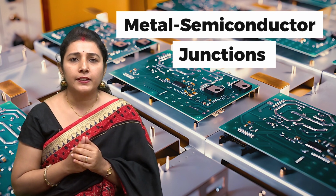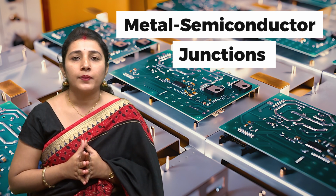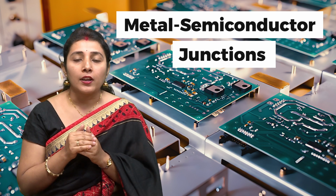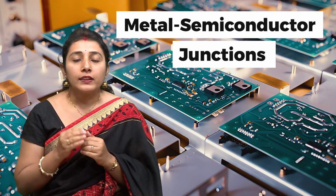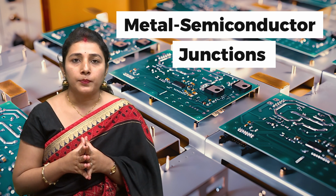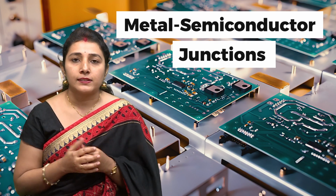If we see an integrated circuit, we will find a layer of p and n regions, and all these regions have to be connected, and we use metals for the interconnects. So, when a metal is connected with the semiconductor, we want that contact to be ohmic. If that contact is ohmic, it will not rectify any signal, and we will have linear IV characteristics for it. Hence, we require the contact with minimal resistance and no tendency to rectify any signals.